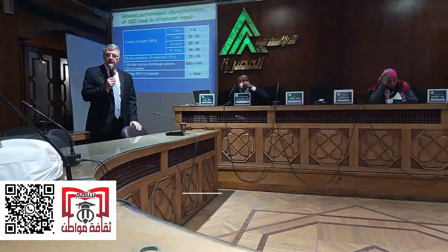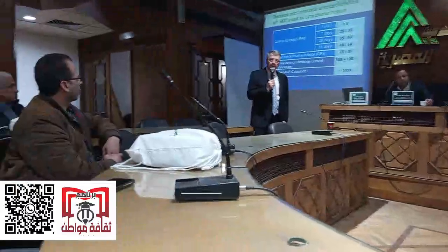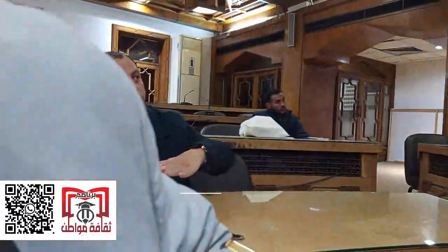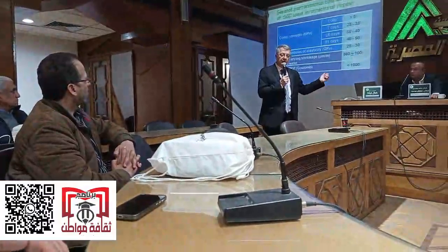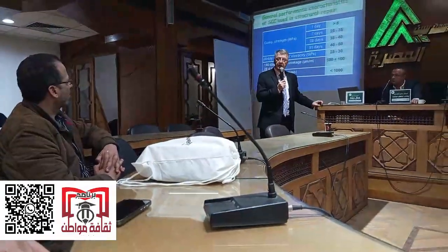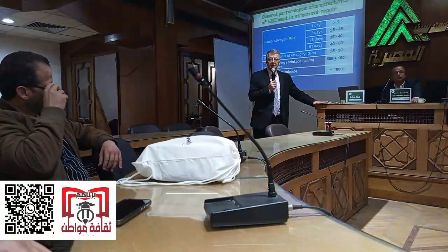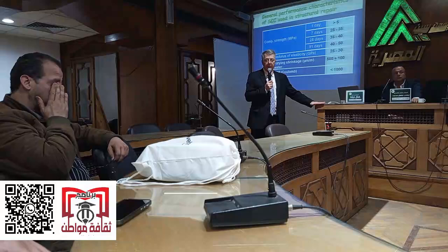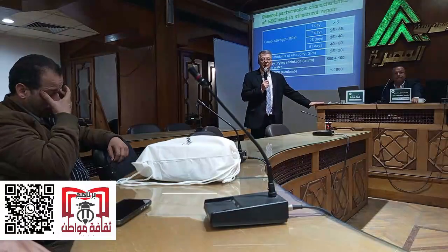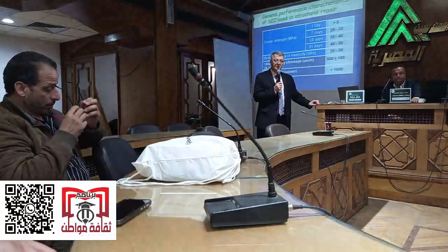I mean, we use it in bridges, right? This one is for bridge decks? No, this one is a repair for infrastructure, for repair of piers, walls, retaining walls, and girders. But if you want to use this for vertical construction, we can reach 40. In this case we can reach 40 megapascal for concrete. I mean, 40, you can, 45 also, like this.